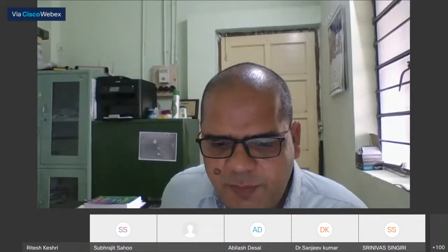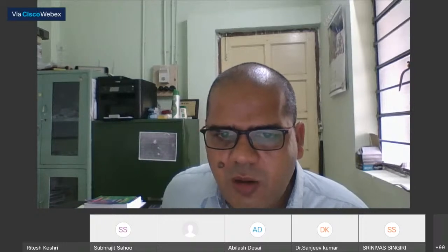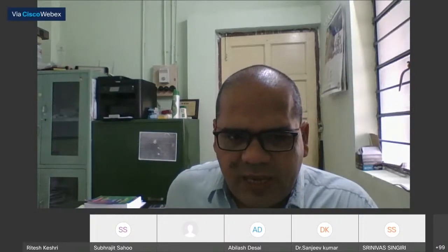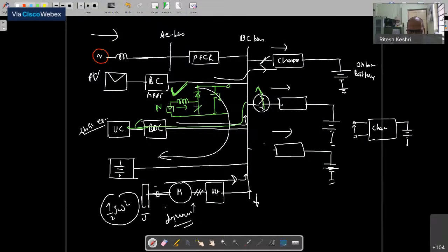No. The transient peak is there because in each cycle of the operation, see, when you disconnect it, do you think that this current will fall down immediately? No, and you cannot keep this switch permanently off. So what you can do is completely turn it on, so this current will pass through this one completely. But if you do this, maybe you have not sized your switch accordingly, it will burn out.